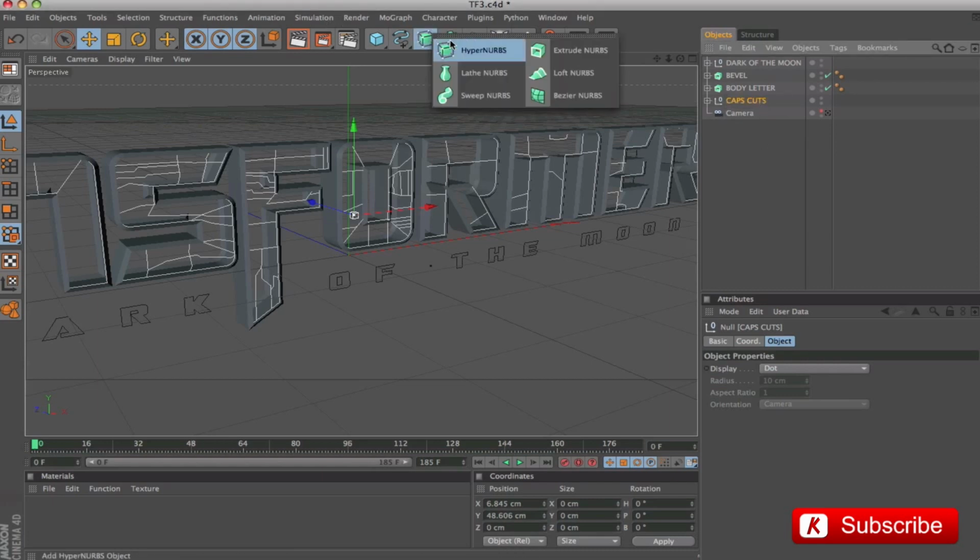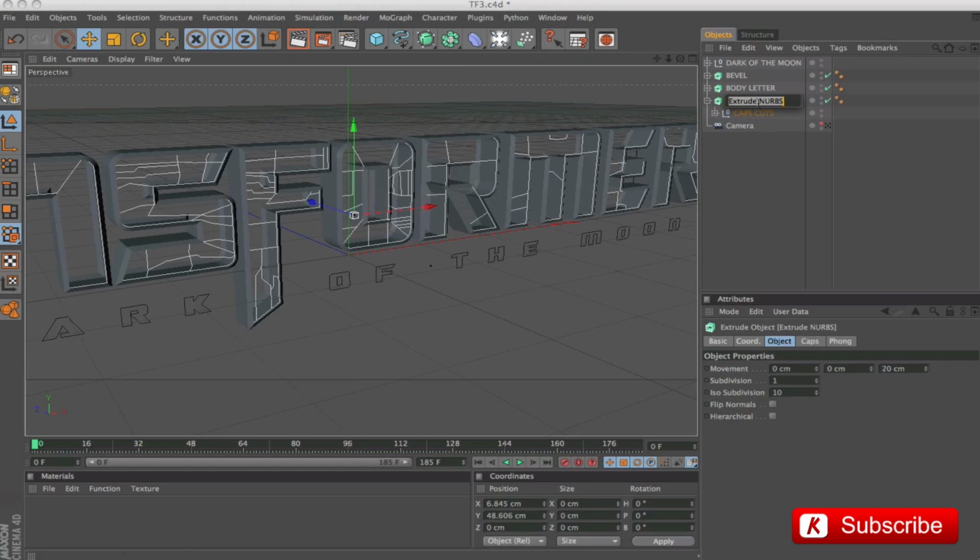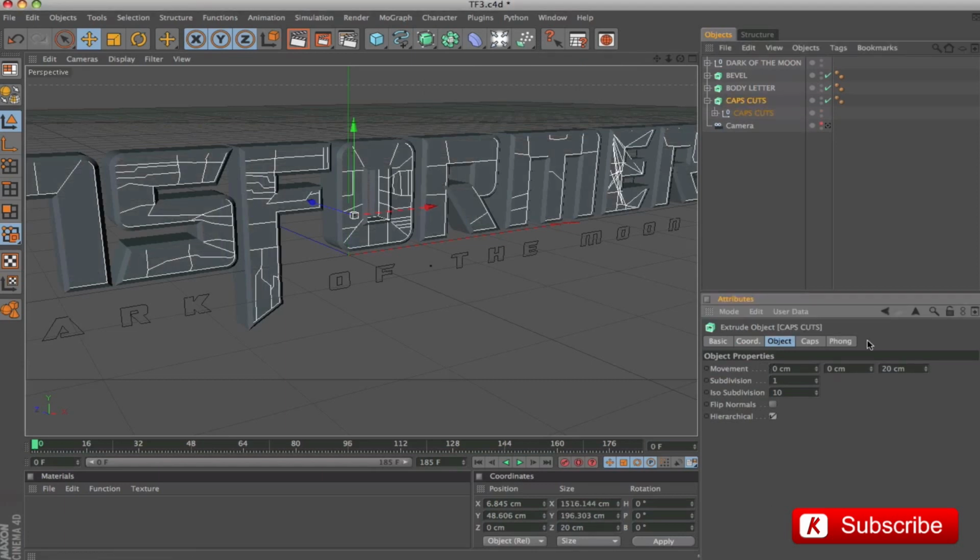We select the caps cuts layer, and apply an extrusion. Depth, to 4.25. In the Coordinates panel, we insert in the Z position, minus 4.25.